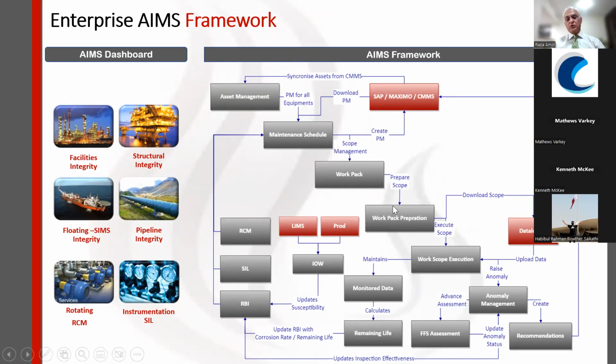And you can create all your work packs once the inspection schedules are done. This is a very lengthy exercise, and it needs to be meticulous in ordering, providing the sequential ordering numbers, as well as getting the right methodologies used for each of the inspection types. API defines that. You should have a library within the system that you can pull through and auto-generate all of the work packs. If you do that, you can get a very consistent approach.